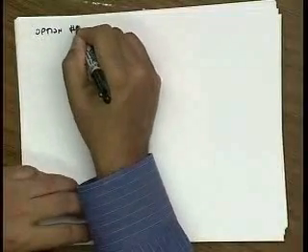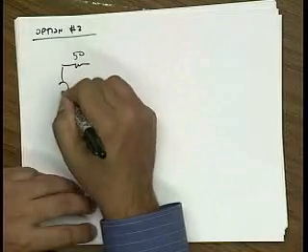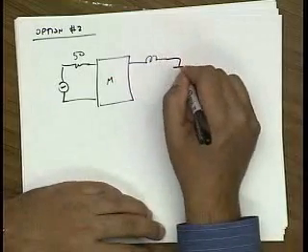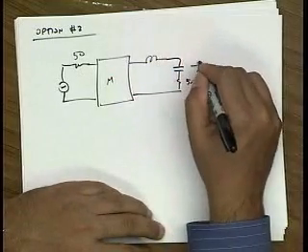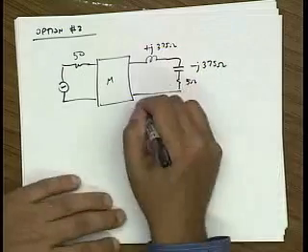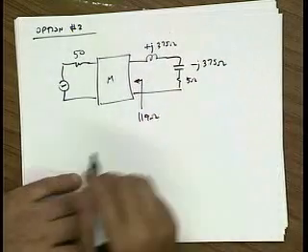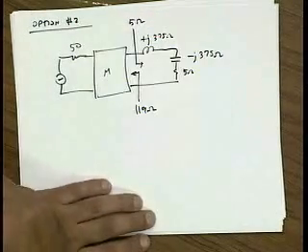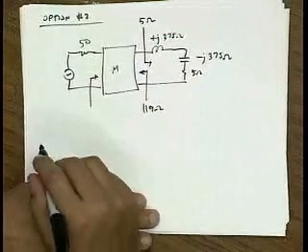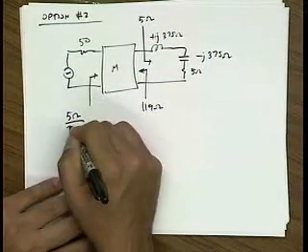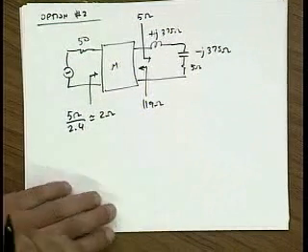All right. Well, let's try something else. Call this option 2. Option 2 is I still would like to get that great noise figure, but I'm going to put an inductor here to resonate out this capacitance. So this is minus j375 ohms. I'll make this plus j375. I still use a matching network, so I get 119 ohms, so I get that great noise figure. But now looking into here, I see 5 ohms at resonance, right? And this gets transformed down by a factor of 2.4 roughly. So looking into here now, I see 5 ohms divided by 2.4, or about 2 ohms.